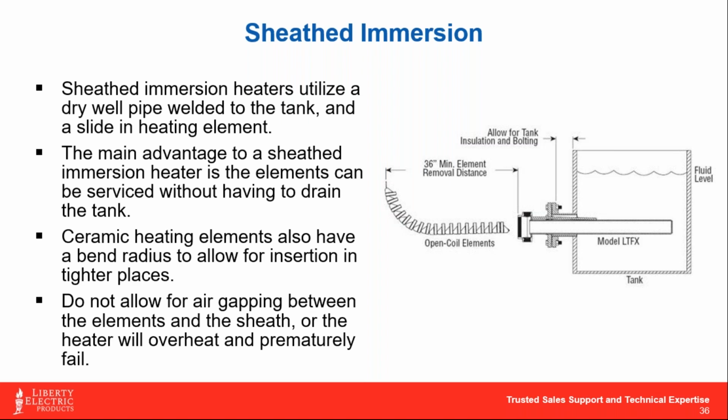A lot goes into having to bring another tank or some sort of portable reservoir on site to make that happen. So this can become a very, very convenient cost of ownership type of product, where you can very easily insert heaters into that protective sheath and rewire them within a half hour and be up and running, versus taking literally a couple days to drain a tank, change the heater, refill it, and go through that process.